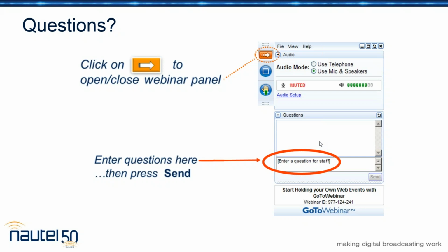David asks, when it switches to analog audio left-right, does it generate stereo? Good question, and the answer is yes. We have a built-in stereo generator in this transmitter. So yes, in fact, it can. We can generate stereo whether or not we're coming in with AES EBU, or we're coming in with analog left and right, or with the internal Shoutcast, Icecast, and or audio player functions. The stereo coder is built in and can be configured to operate.